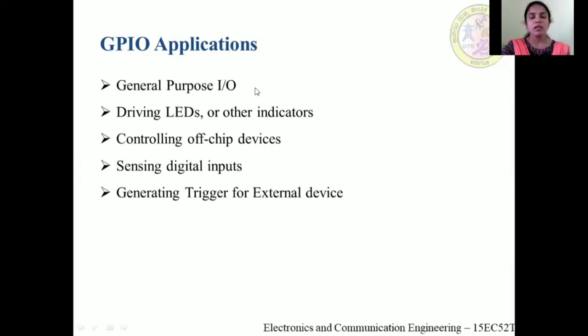For example, if you are going to manufacture a mobile using the LPC2148 IC, we have to connect an LCD display, LED indicator, keypad, speaker, real-time clock, like that. If you want to connect any external peripherals to the LPC2148 IC, in that case we are going to use these general purpose input-output pins.